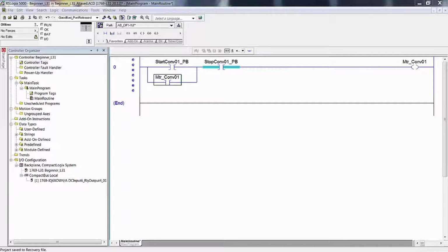But it would be much better if before the I/O was even assigned, meaning before the I/O sheets were even drawn, you gave a list of the I/O needed to whoever is actually drawing up the design of the control system, drawing the configuration for the I/O, to show them what you need and let them then follow your list. What we're suggesting is that the dog wag the tail, not the tail wag the dog. And I'm sure people who design control systems feel they're the dog and the people that program are the tail. However, whatever the designer does, the programmer is stuck with it. So do yourself a favor, get used to using concurrent engineering, writing your programs without using the I/O assignment.